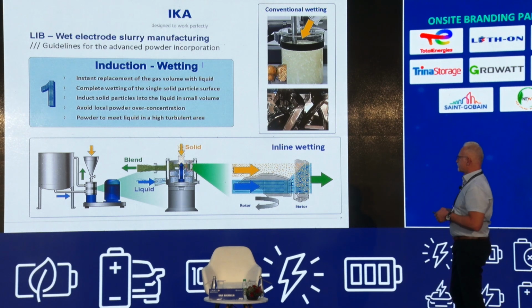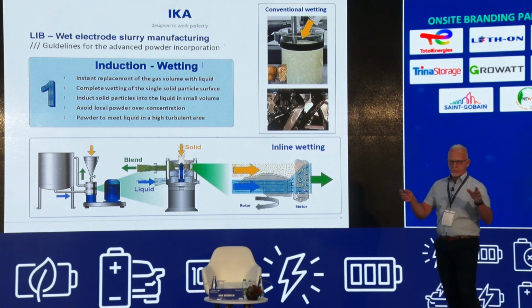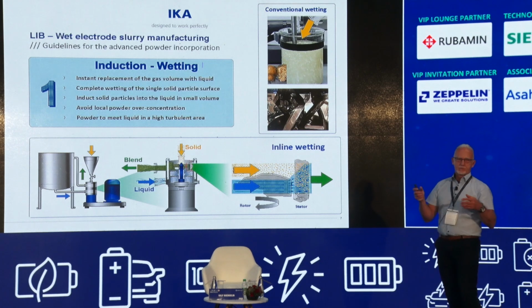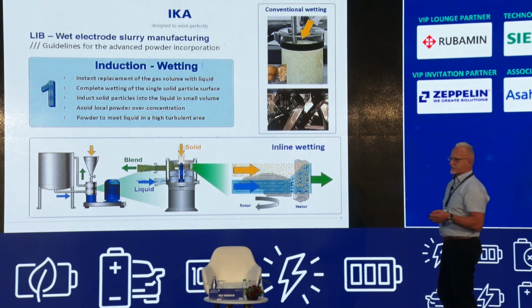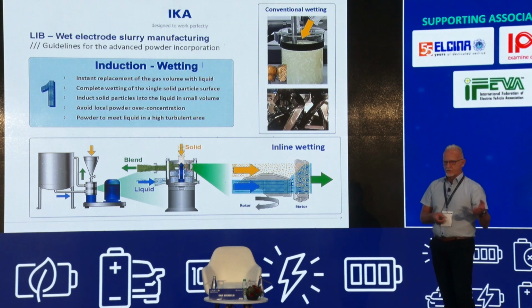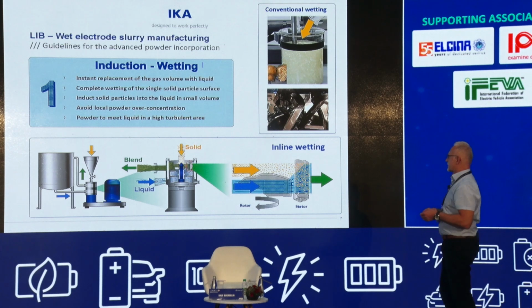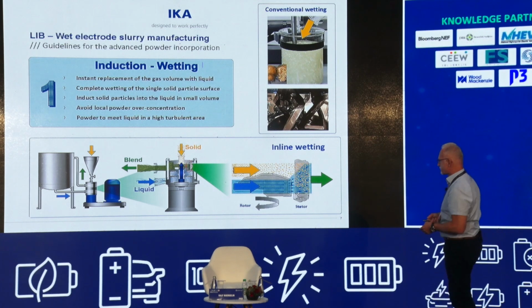Another thing is, if we just pour it into a mixing vessel, often the powder material sticks on surfaces and is not really in the product. So you have a loss in the final product, or agglomerates which peel off after some time, and the material sticks then in the filter, but it's not in your final slurry.